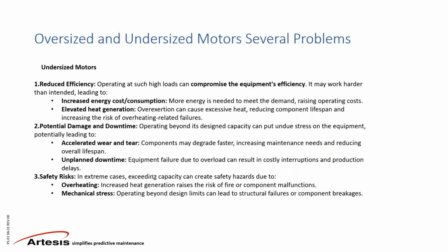An undersized motor is an even bigger problem, because with an undersized motor, your motor cannot actually meet the load demand. So it is now running under stress and trying to work harder to do the same job. And of course, it is consuming more energy than it needs to, and the motor will run hotter.